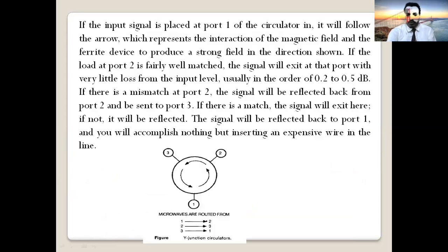So to revise what we have discussed, a circulator is a passive device. Internally, there is a magnet, because our signal is an electromagnetic signal, it interacts with the magnet. So the magnet guides the signal only to one port. So what type of circulator is this? There are two types. We said this is anti-clockwise, right?